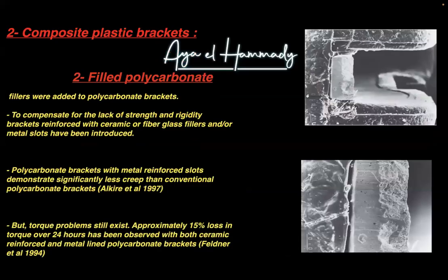What about here the filled polycarbonate? Okay, the polycarbonate here is to compensate for the lack of strength and rigidity of the oxymethylene one, okay? And also, we can add a metal component in the polycarbonate one, okay, to reinforce the slot.